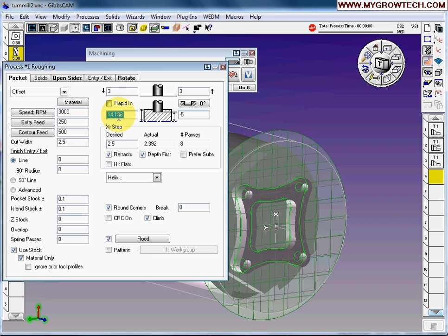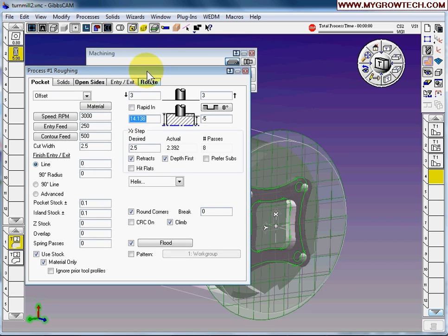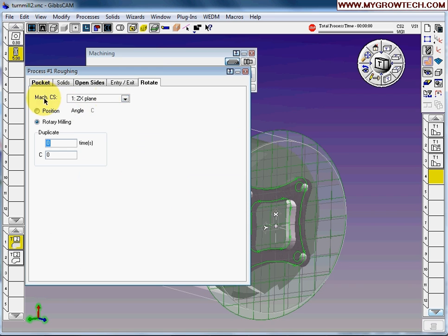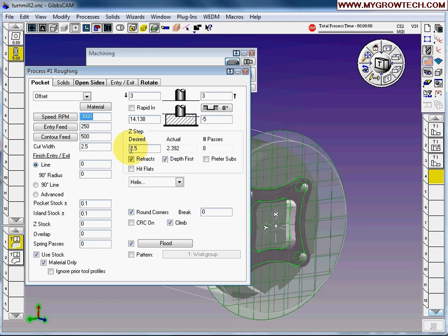We got some mistake. This is because we forgot to change the machining plane. So you must change the machining plane, the coordinate system, to be XY also before you do any changes. Again, let's check again. Use alternate key, select this face. It will be 0. Let's put 1. Let's check again, and we're going to machine until the bottom face. There will be minus 5.